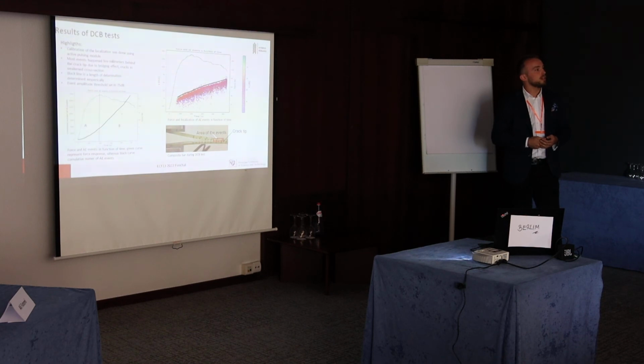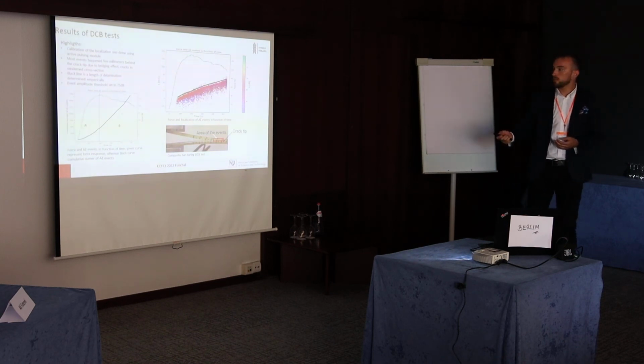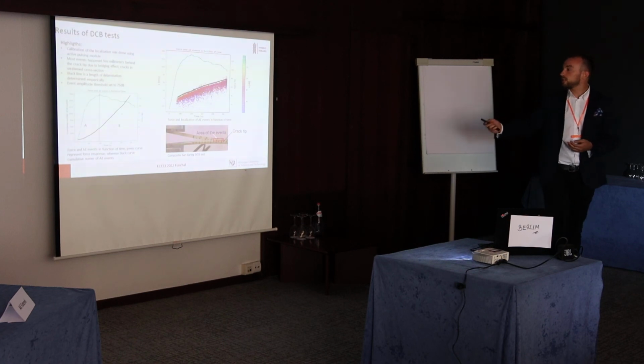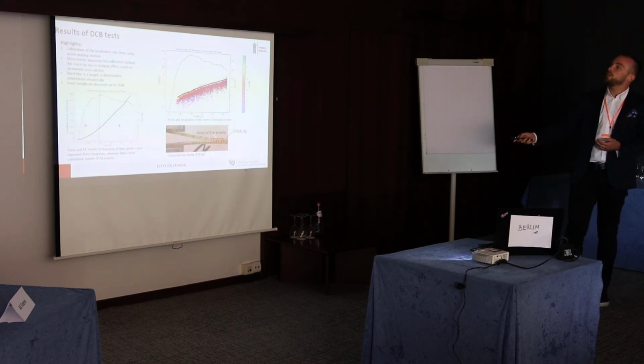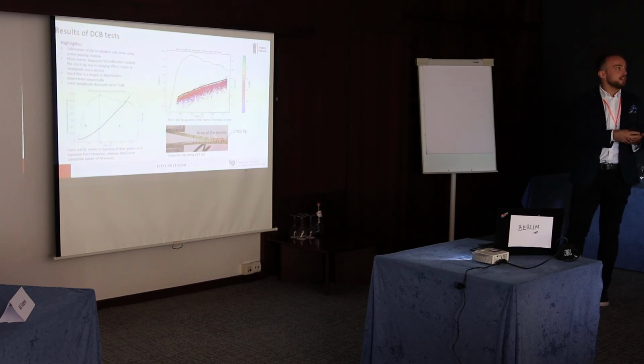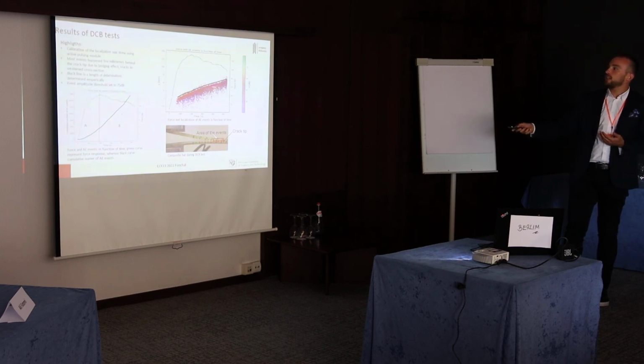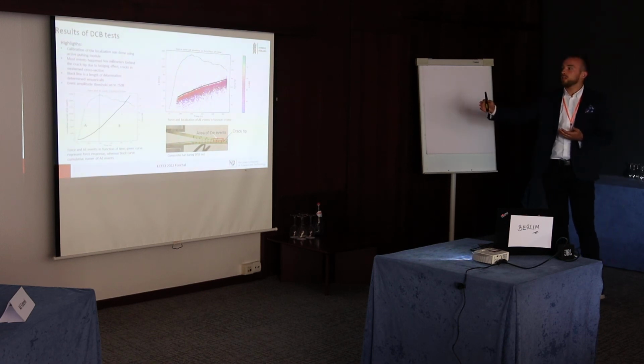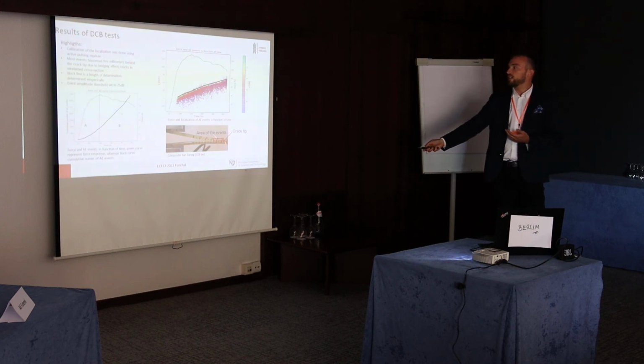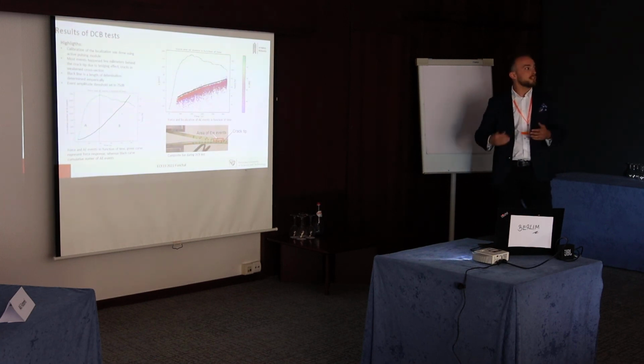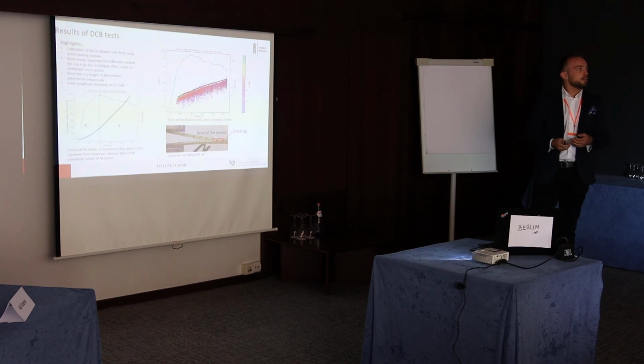Yeah, and why have you used two sensors? Were you trying to make the location? Yes. Here is the location. Maybe I didn't talk about this. The black line is our empirical measurement that we made by eye, and these are the acoustic emission events. And all of the events which we measured were in this area. This is the crack tip that we can see, and the measurements were in this area, 20 millimeters behind the crack tip.